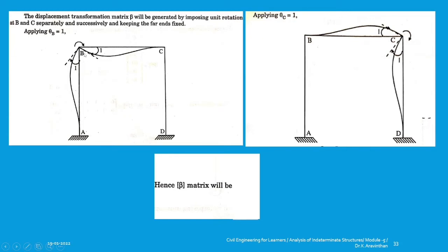You can twist this joint and it doesn't resist the moment. Hence, the mode of application of the load will be moment. What is the possibility of movement? That is, what is the possible kinematic indeterminacy? One rotation could happen at joint B and one rotation could happen at joint C. So this is Ki. Now you have two number of Ki, one at joint B and one at joint C.